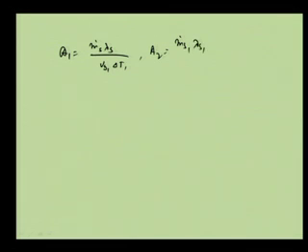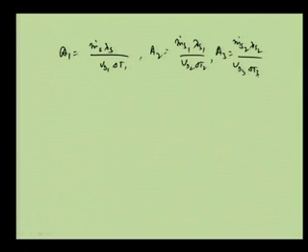So, by knowing delta T, we calculate areas like this: area 1 will be ms lambda s by UD1 delta T1, then area 2 will be equal to ms1 lambda S1 by UD2 delta T2, and area 3 we will calculate as ms2 lambda S2 by UD3 delta T3. By this way we can calculate the areas again and see whether the areas are correct or not.